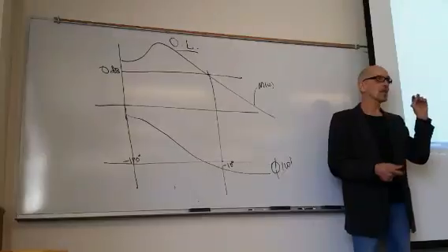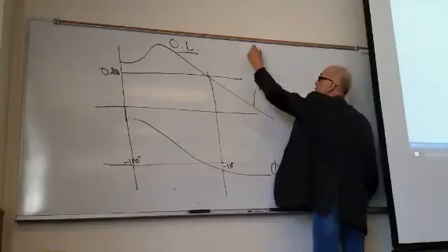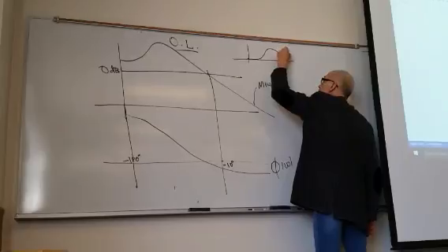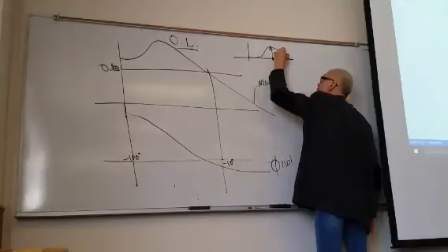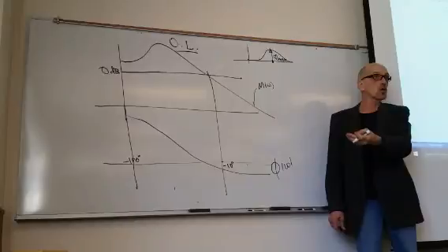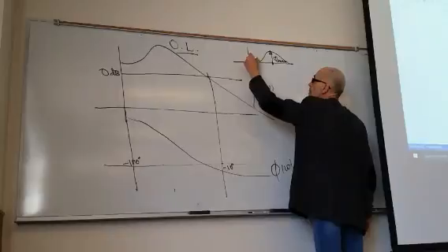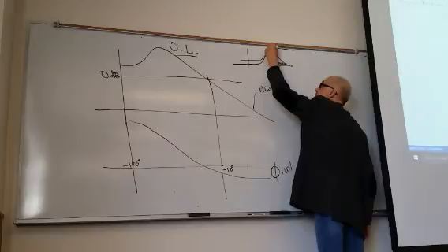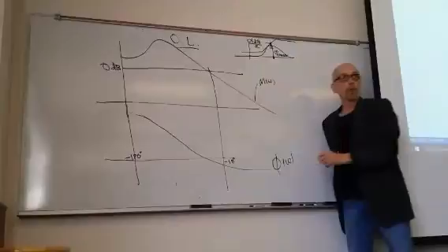The key thing that some people don't catch right away is the fact that this compensator looks like this. On log frequency axis, there's your phase. This is what you're designing for. This is my phi max, right? I got phi max of 40 degrees because I had minus 10 and I wanted 30. Right? But also when I apply that thing, the magnitude goes from here up to here, up to here. So the amplitude is increased by alpha dB over 2.